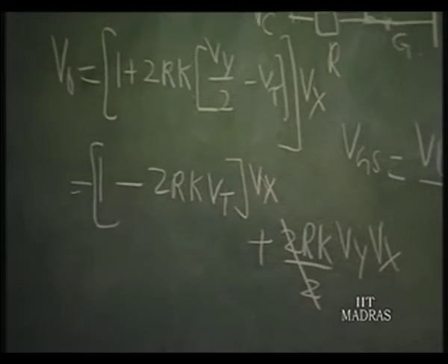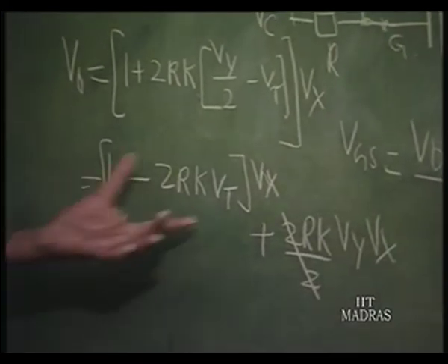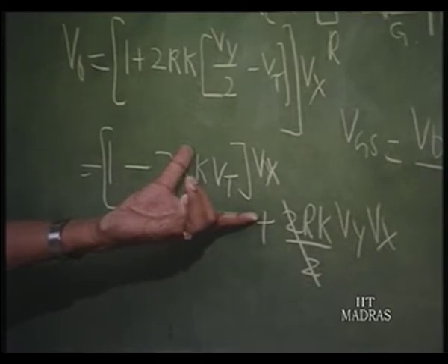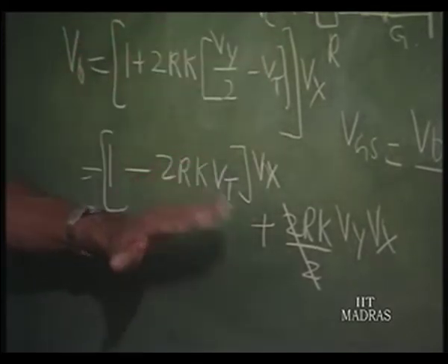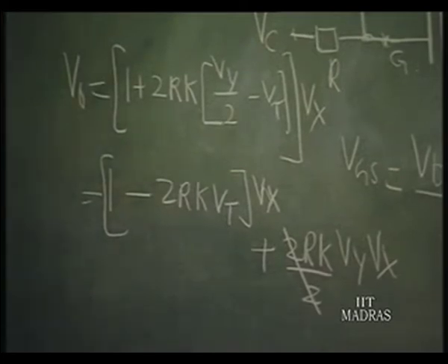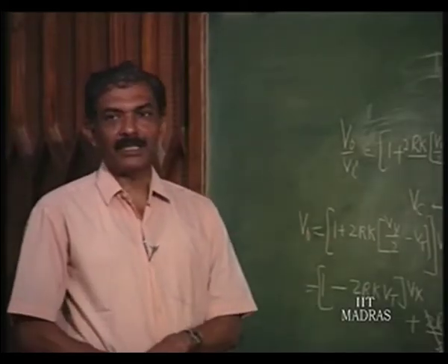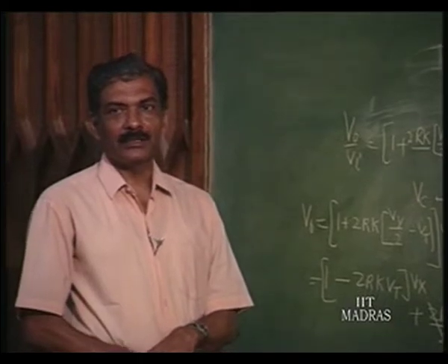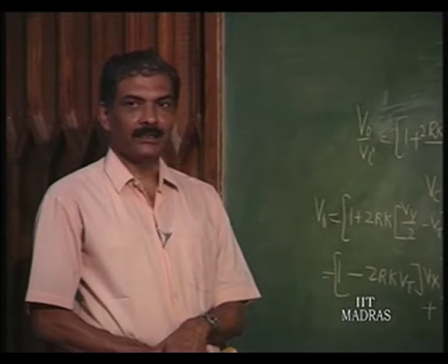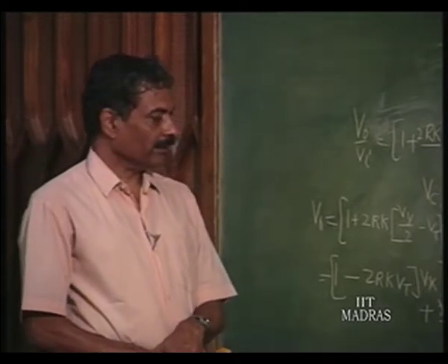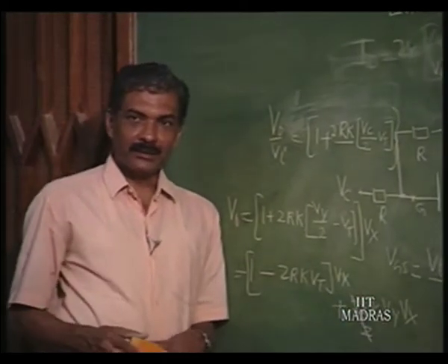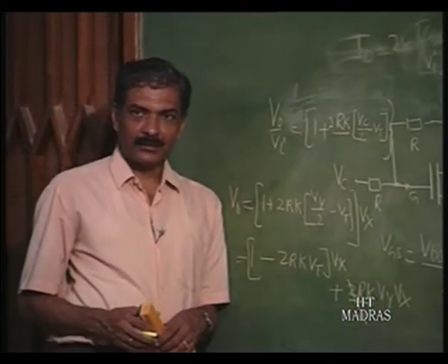This is the product component, right. So, we can get rid of this by using a subtractor. So, you can design multipliers using such voltage controlled amplifiers also, wherein a field effect transistor is used as a resistor. So, this can be easily done, and multipliers of this type are commonly built in discrete circuit design.